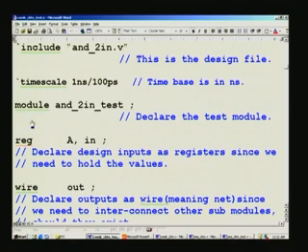Notice that there is no input or output declaration here, because this happens to be the topmost level and there is no higher level than this. Everything is contained in this level. So, what is the need for any IOs? IOs imply going to the external world. Mind you, what we are doing is making a chip.